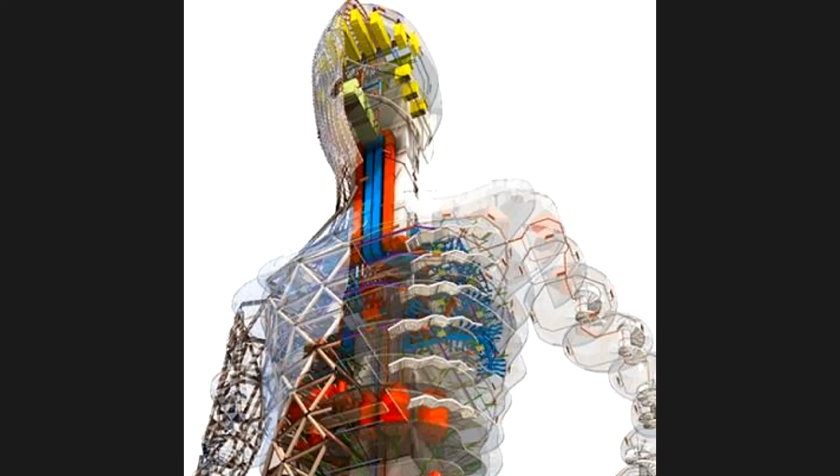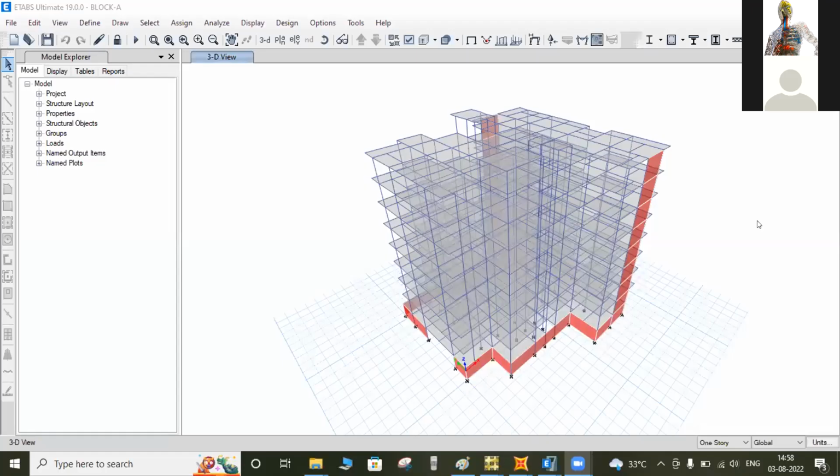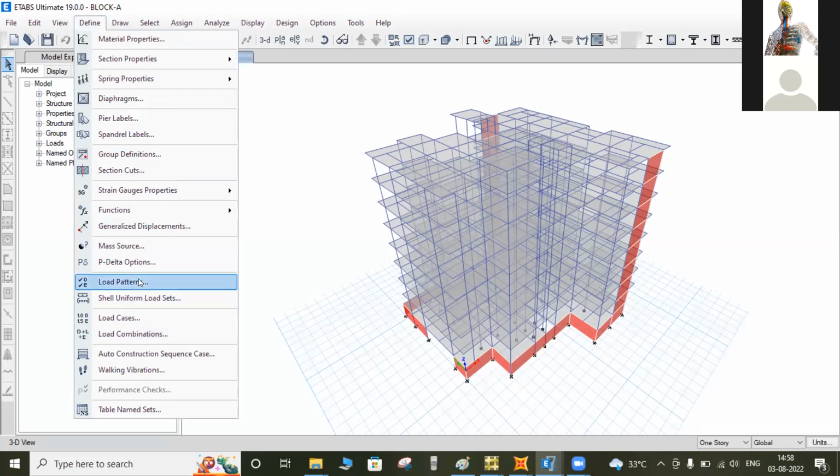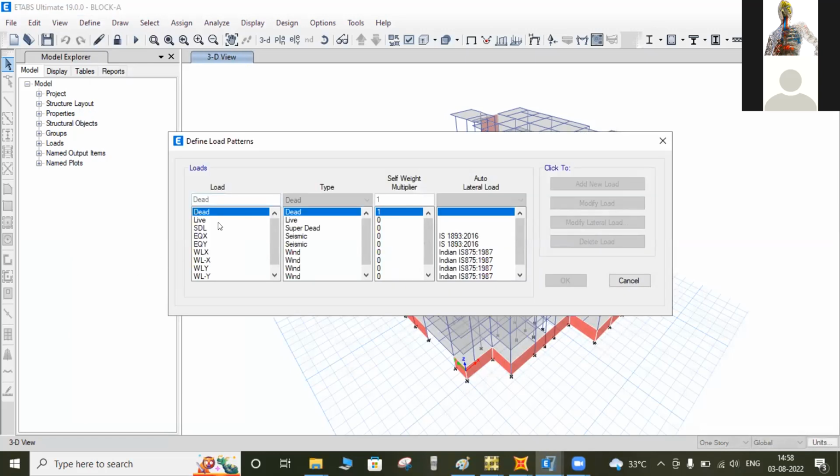Okay. Hello, Karim. Kindly explain again. Yes, okay, sir. So finally, when we complete the modal analysis, we calculate the external forces like the gravity loads, frame loads, area loads. We calculate as per our materials and finishing requirement for the architecture. So when we move to the define part, we define the patterns, which patterns have to be considered. You can see that one which represents the self-weight, on behalf of which we are performing the modal analysis.